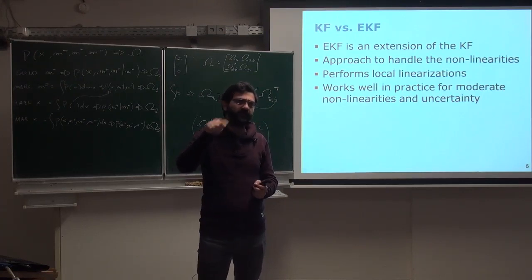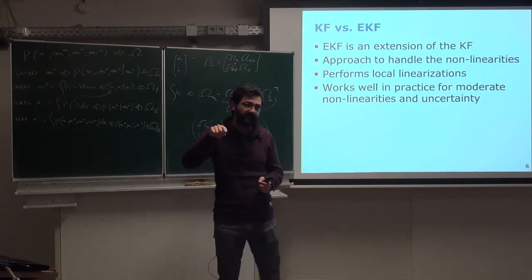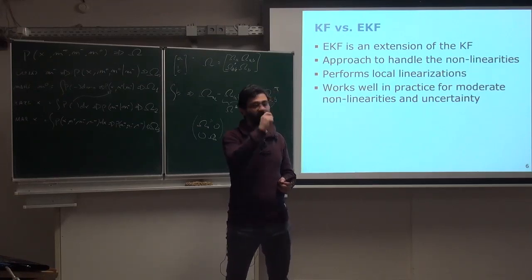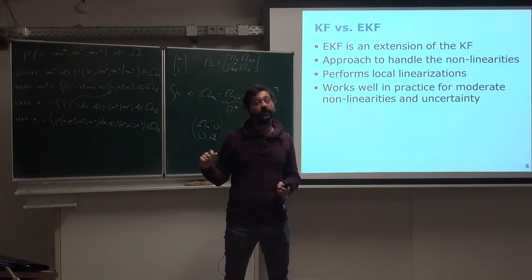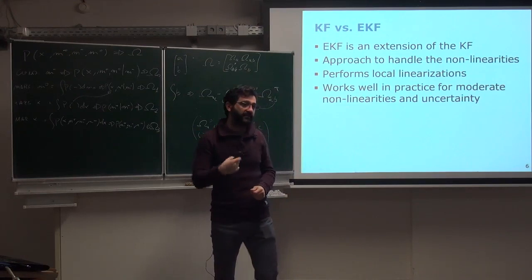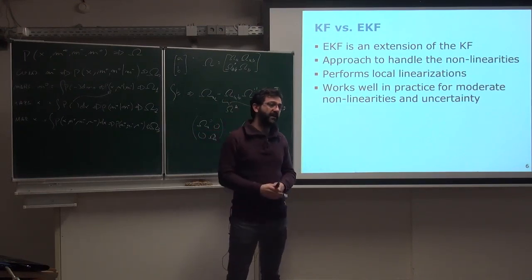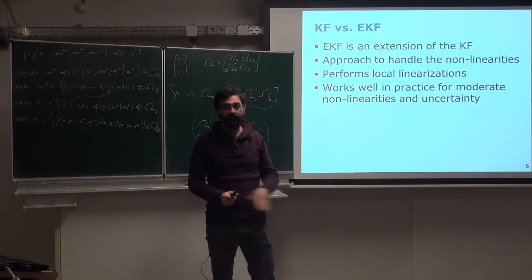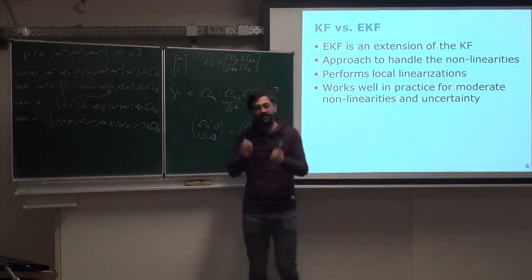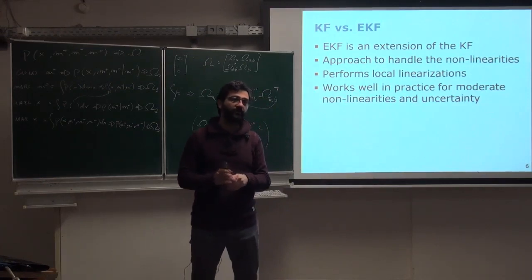I think it's called the iterated extended Kalman filter, where you try to get better linearization points than your actual one. So imagine that for the motion update, you compute the function, and then you slowly get an approximation, going down a bit, down a bit, and the same thing for the update part. But this is completely out of the scope of this lecture.